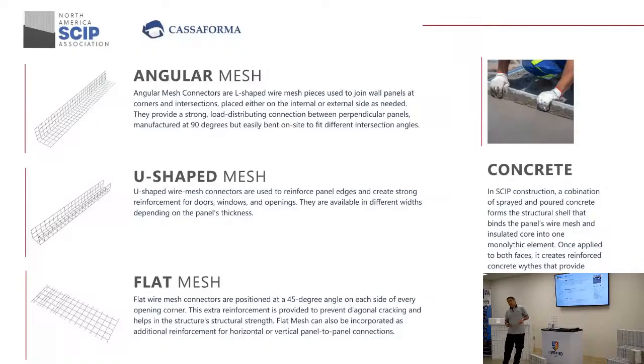To be honest, if you project the mortar over the foam, it will stick, but it won't have any structural capacity. Okay, so if there's a tiny space that you need to spray the mortar and you don't want to place the mesh, it can be done. I don't suggest that, but it can be done.